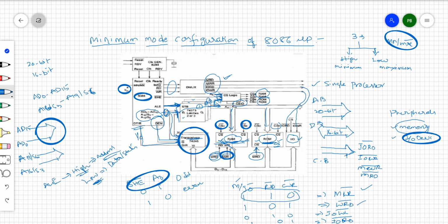So the data enable pin tells you, if it is 0, data is enabled on this particular data bus, right? These 2 control pins are going to work together with this bidirectional buffer. Like that, this is going to provide bidirectional data transfers through these bidirectional transceivers, right?